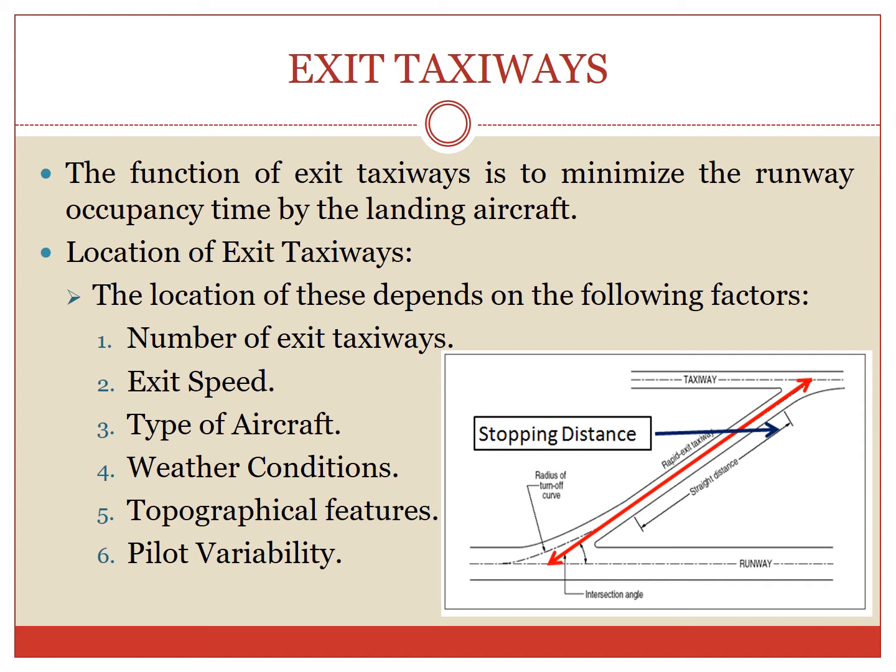To determine the distance from the threshold, the following factors are required. First is the number of exit taxiways, the exit speed, the type of aircraft needed, the weather conditions, the topographical features, and the pilot variability.